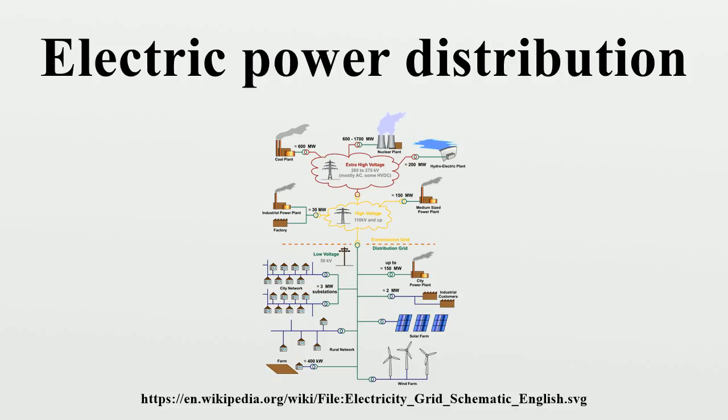Introduction of alternating current. The competition between direct current and alternating current was known as the War of Currents. At the conclusion of their campaigning, AC became the dominant form of transmission of power. Power transformers, installed at power stations, could be used to raise the voltage from the generators, and transformers at local substations could reduce voltage to supply loads. Increasing the voltage reduced the current in the transmission and distribution lines and hence the size of conductors and distribution losses. This made it more economical to distribute power over long distances. Generators could be located far from the loads.